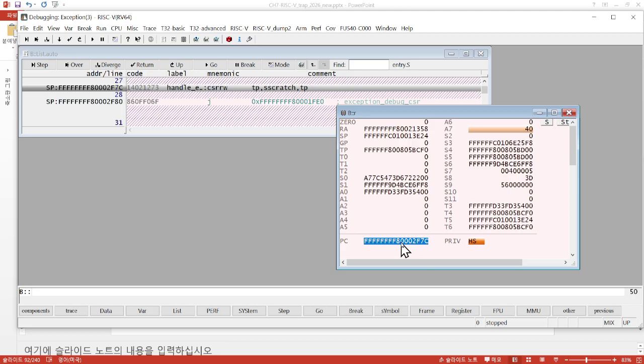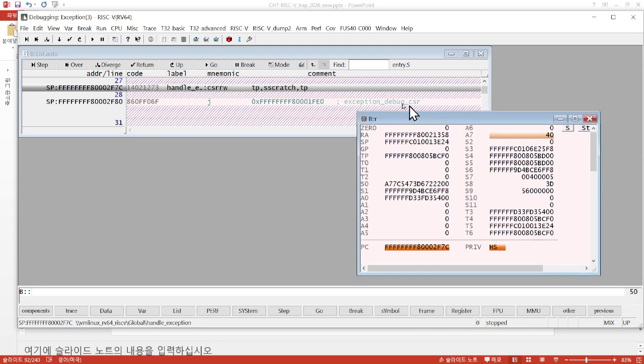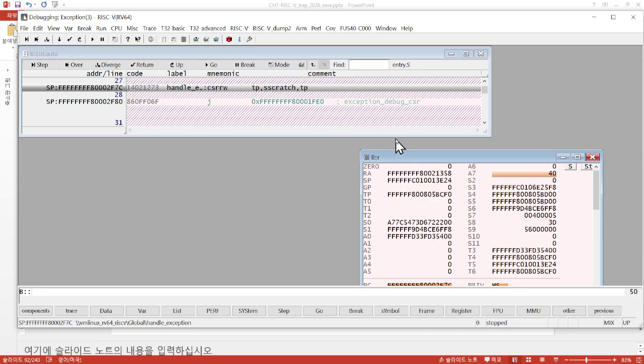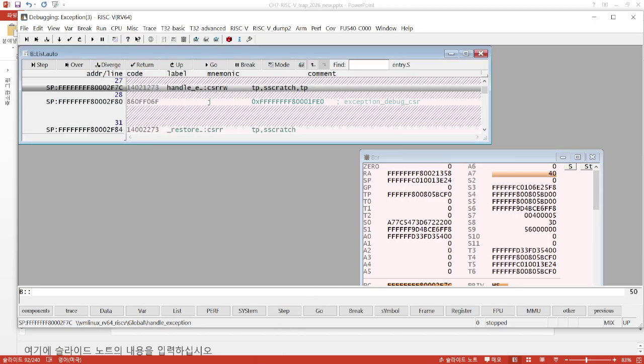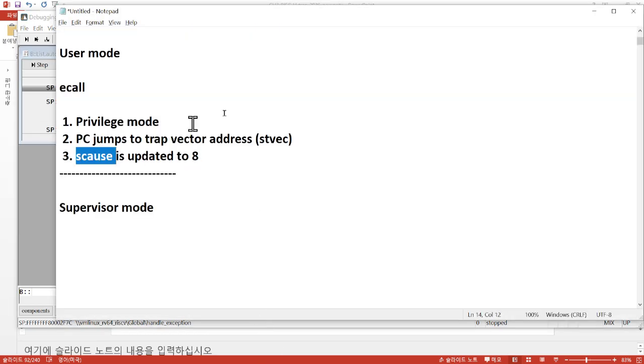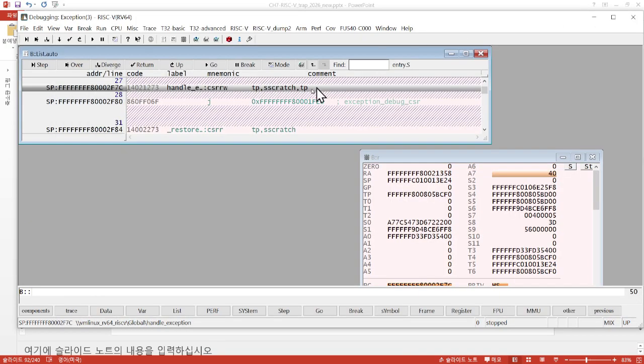This is the typical pattern of a virtual address in the Linux kernel. If the Linux kernel is running on the RISC-V base system, the virtual address starts with this kind of pattern. Now we will check another important debugging signature, the value of the supervisor cause register.